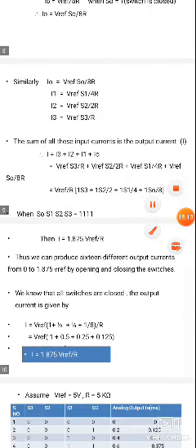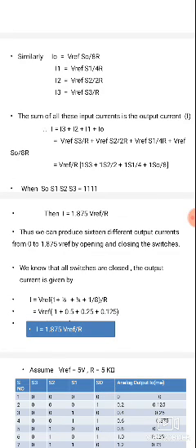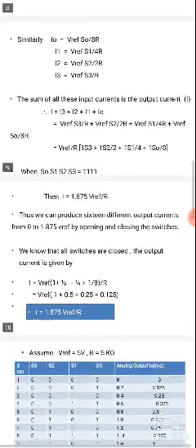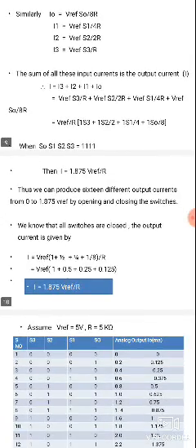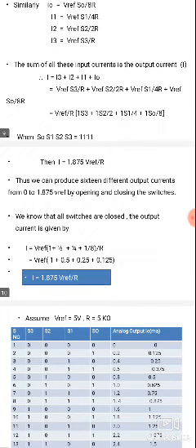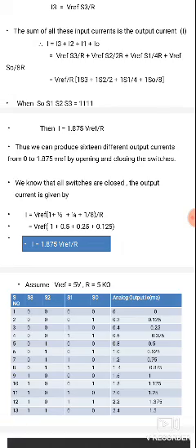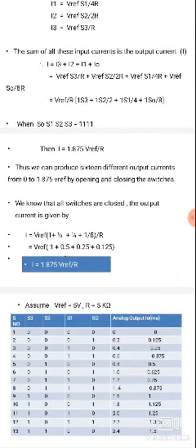Next, I3 is the condition where the MSB switch equals 1, that is, the most significant bit of the circuit equals 1. So whenever S3 equals 1, the current across switch 3 is I3. The resistance across I3 is R, so I3 equals V reference into S3 by R. S3 is the switch 3 position, I3 is the current across switch 3, and R is the binary weighted resistor.